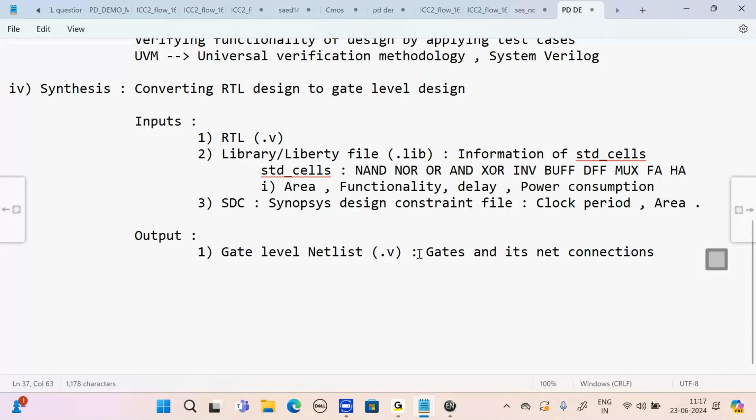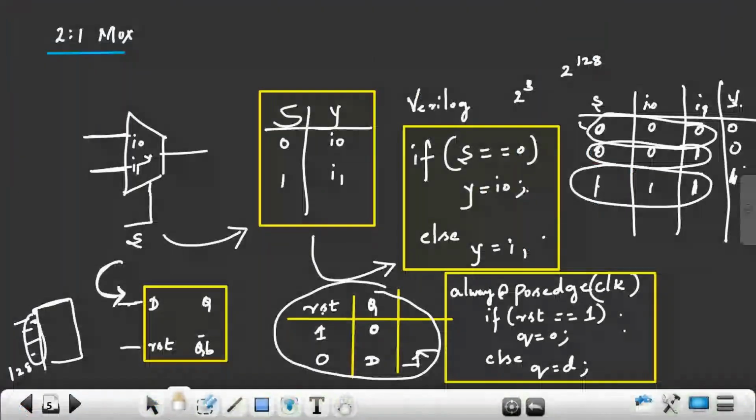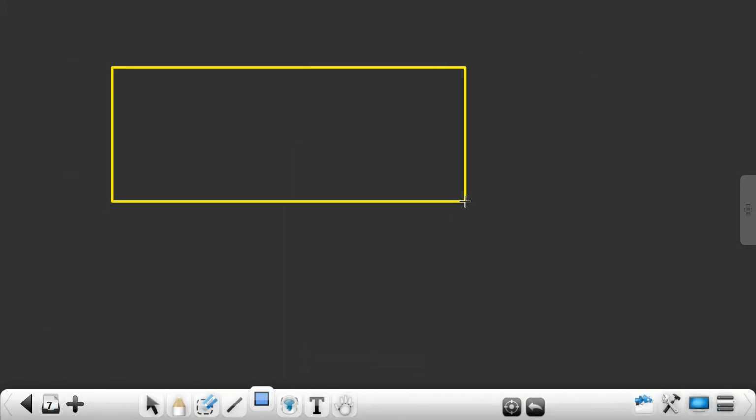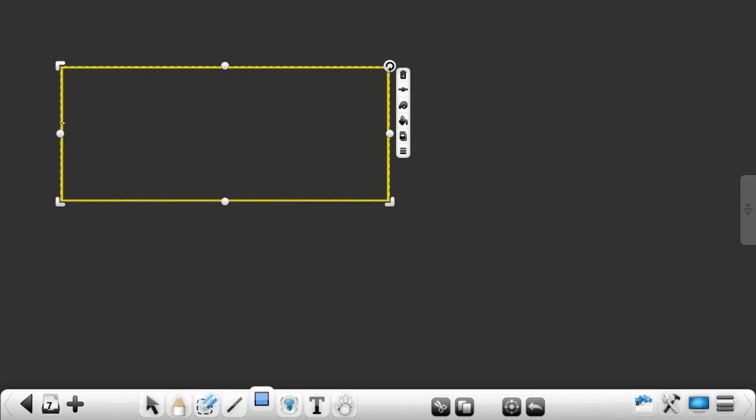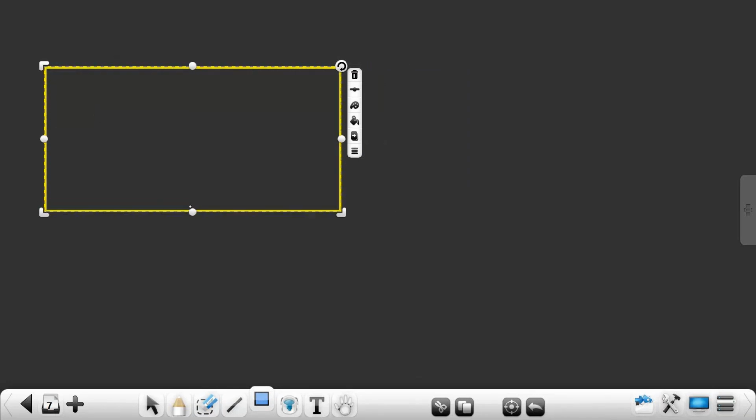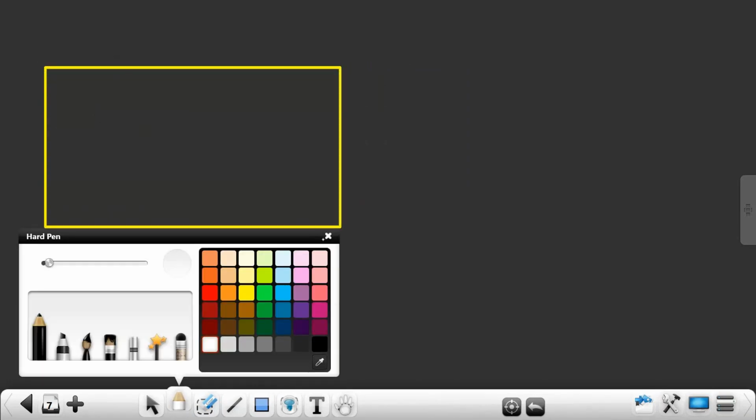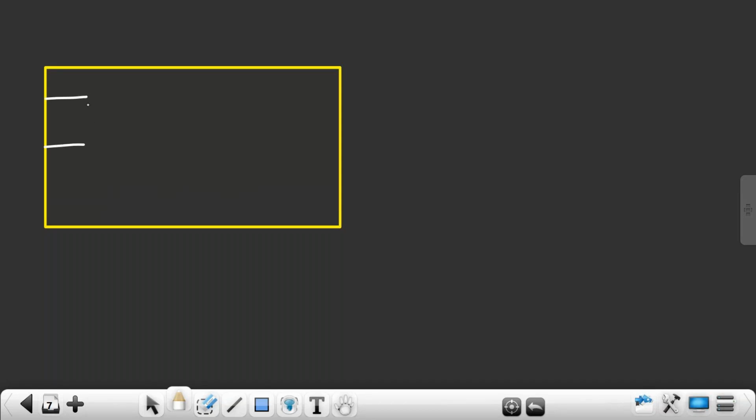What is present in gate level netlist? You take this example. So now this is your design. You assume this is your design. So this design has first one AND gate, A, B, Y. This I'll call it as input M, N. M, N is a port of my design, input ports.